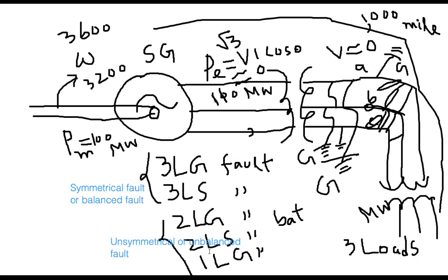So what is the other type of impact? They will create zero sequence current. If you remember chapter 2, 3-phase circuits at the beginning of the semester, they will cause zero sequence current. And that zero sequence current will flow through the neutral of the system.